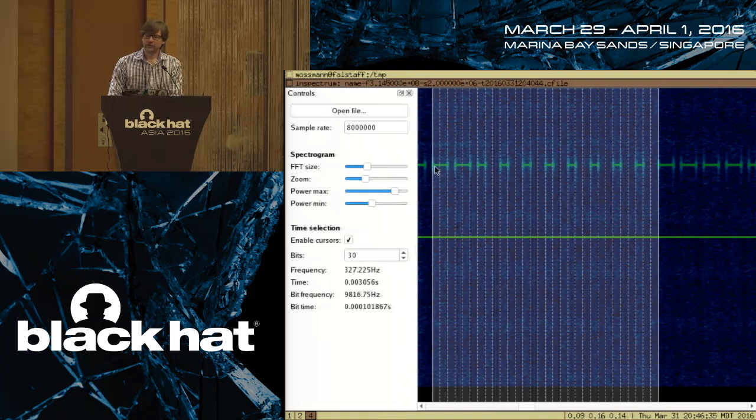The long pulses are on, off: 2 on, then 1 off. The short pulses are on, off: 1 on, and then 2 off. And it's very consistent like this. So I'm going to call this 1/3 of a pulse period, this 1/3 time unit, a symbol.